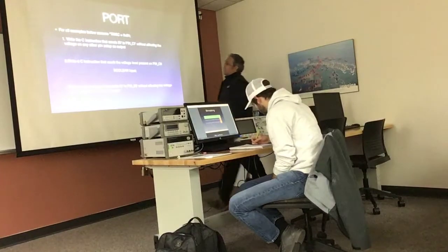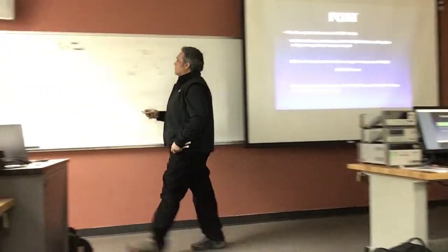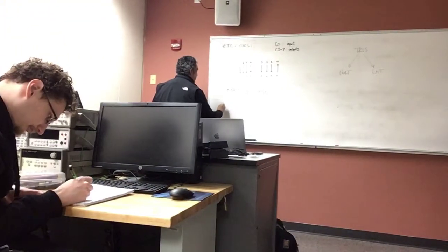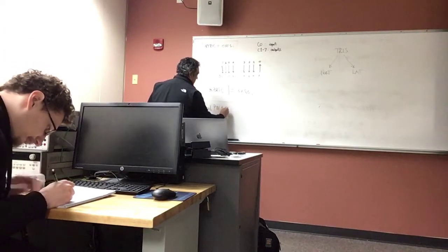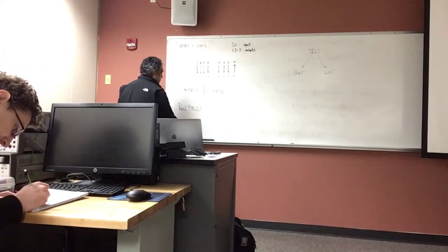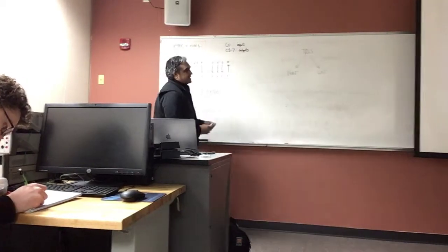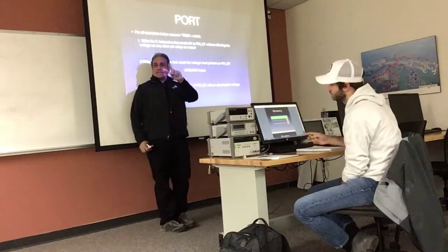All right? Okay, so how do you read pin C0? Well, I'm going to use a read operation. So I'm going to put here read pin C0. So I'm going to take input as the variable that is given to you. A Boolean variable means that it's a single bit variable.